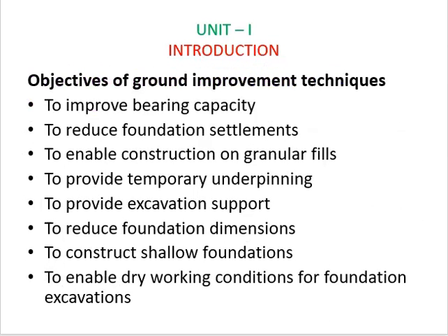Then what are the objectives of ground improvement techniques? The objectives may be one or more depending on the structural requirements. It may be to improve the bearing capacity of soil, or to reduce foundation settlement, or to enable construction on granular fills, or to provide temporary underpinning, or to provide excavation support, or to reduce foundation dimensions, or to construct shallow foundations, or to enable dry working conditions for foundation excavations.